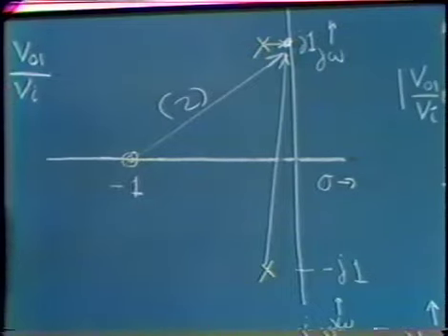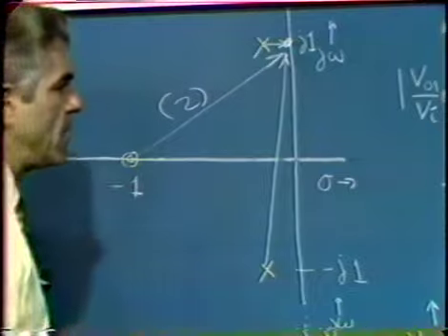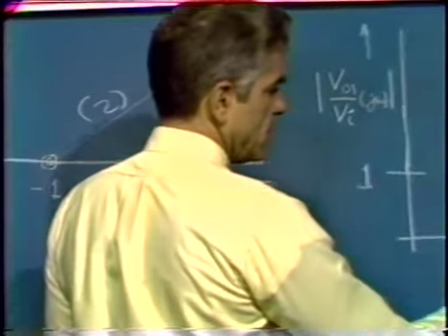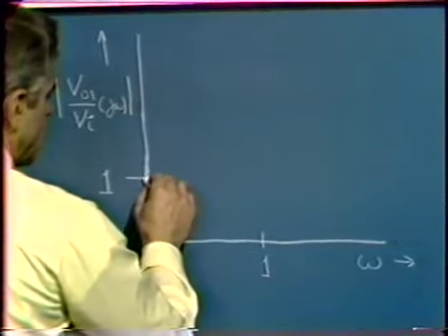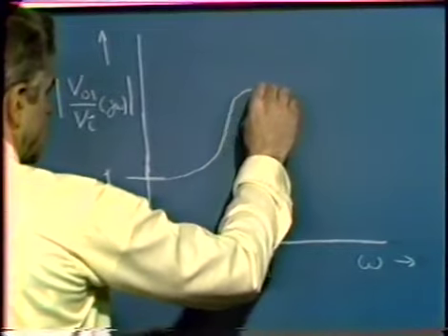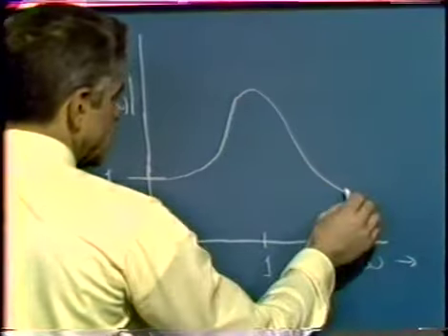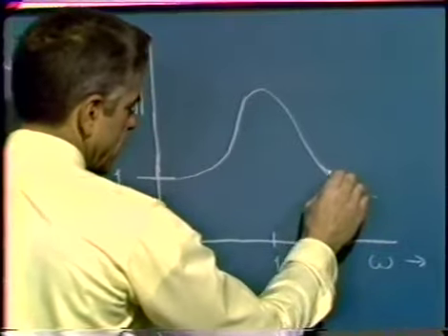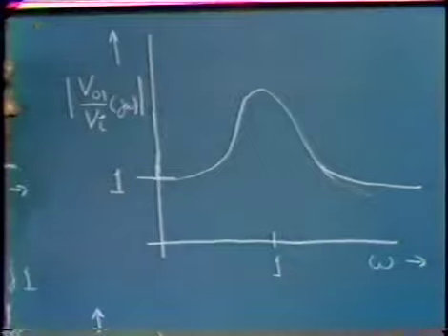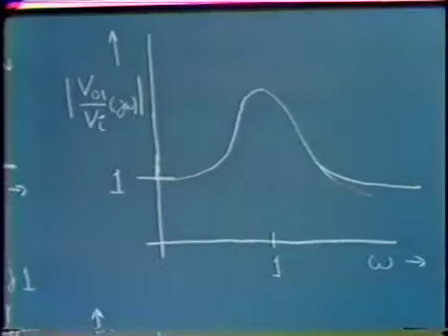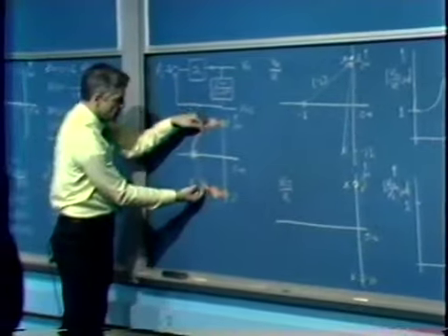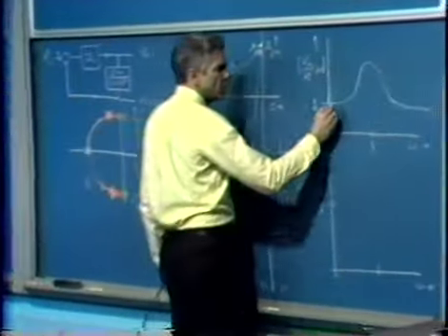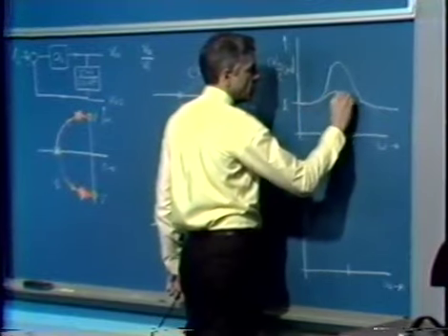in the vicinity of the closed loop pole location, we get a resonance. We argued that the low and high frequency gains are the same, and if we assume that our complex conjugate pole pair were located at omega equals 1, we'd anticipate getting this sort of picture, the usual resonant curve where the high frequency gain again reached 1. And as we lower A0, the resonance becomes less pronounced since these poles move back. We can determine that from our original root locus analysis. So we get this kind of behavior as we lower A0.